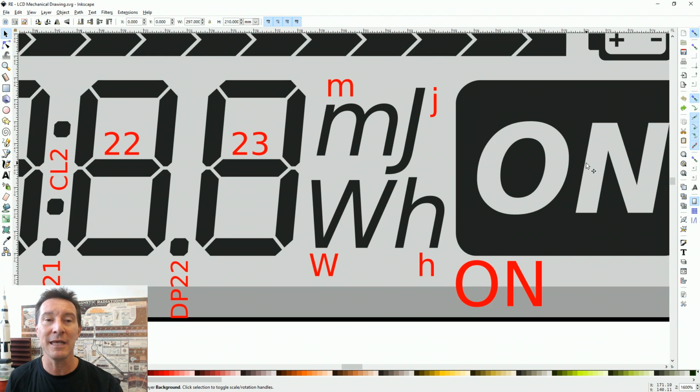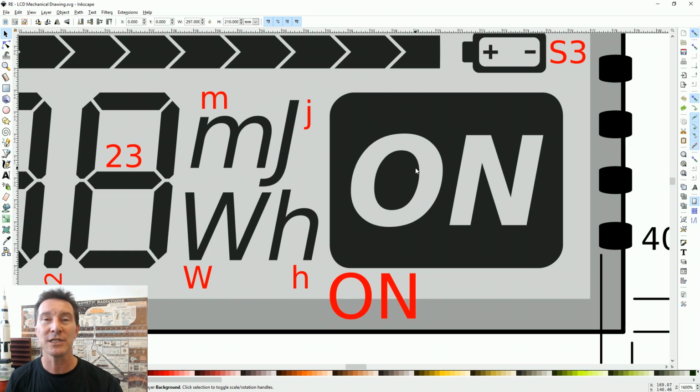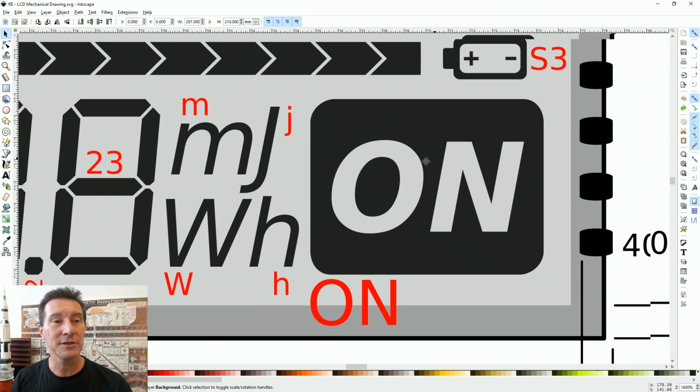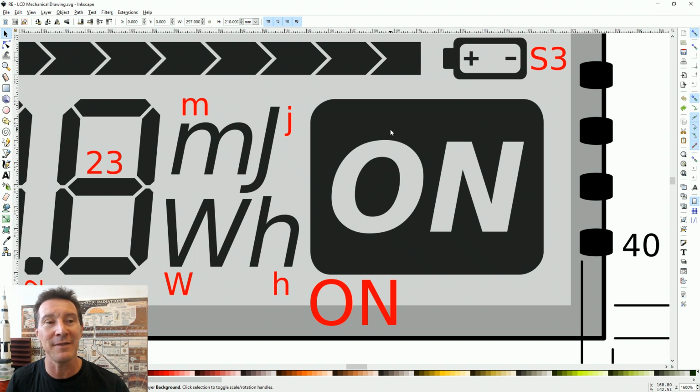And of course, we've got the inverse ones here that just give a nice high contrast. And on stuff like this, you may be wondering, how can they turn on that segment in the middle of the O, for example? How do they get the trace out? Well, because it's the one segment. If you wanted 2 separate segments there, you're screwed, because they would have to have a break in there and have the trace coming out. But because it's the same, they would simply add a very thin conductive trace in there that you couldn't see, and you get all that as one segment.